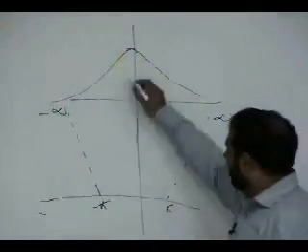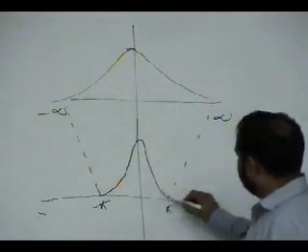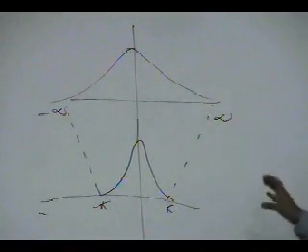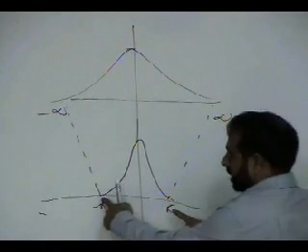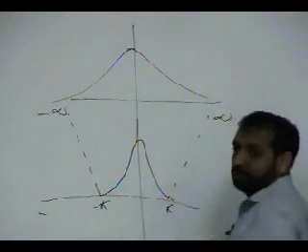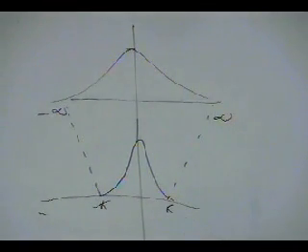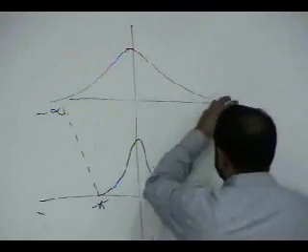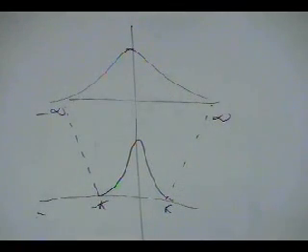It will compress the response, making sure that it never goes beyond minus pi and pi. Now if you replicate this, there will be no aliasing for sure, because you have cut it down and changed it, and it never goes beyond. So minus infinity and infinity will be mapped in the small omega domain into minus pi and pi, so that once you make replicas, they will never overlap.